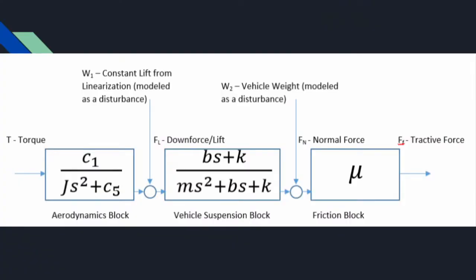In this block diagram, we'll be discussing how the equations of motion of Newton's second law break down the active aerodynamic system. Here we can see that torque is an input, which makes sense because it's directly related to the traction and friction experienced by the tires of the car. So as a car becomes unstable, there's going to be less torque experienced by the wheel. It breaks it down to the necessary downforce to produce the proper friction of the wheels to maintain stability. Since the more downforce there is, there's more normal force being pushed up against the car, therefore increasing friction.